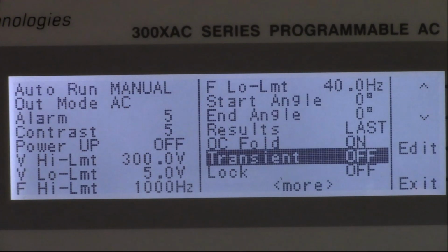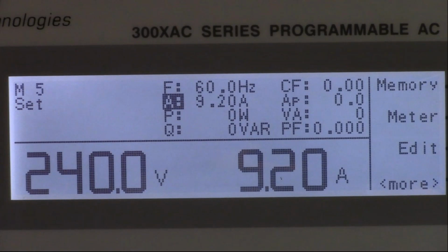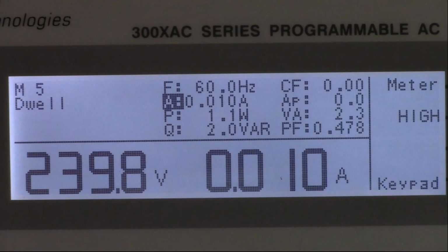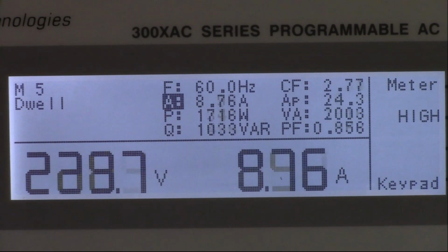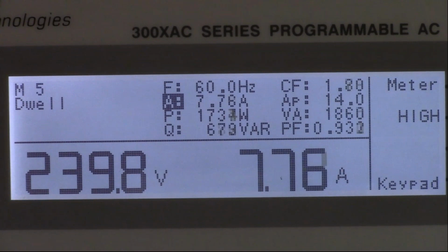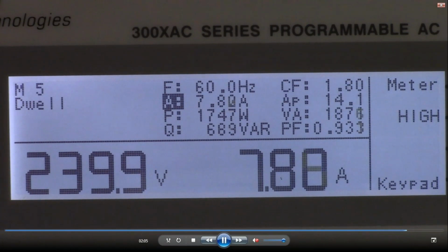In doing so, this allows us to run this vacuum motor successfully past the inrush stage. You can see here that we're applying 240 volts, and then when the motor turns on, it draws 19 amps. So I saw 19 amps come up there for a few seconds. The voltage was dipping, and then what we saw additionally is that now it's at a steady state. So this power supply could meet the requirements for steady state but was not able to meet the inrush requirement. But having OC fallback allowed it to power up this vacuum motor successfully.